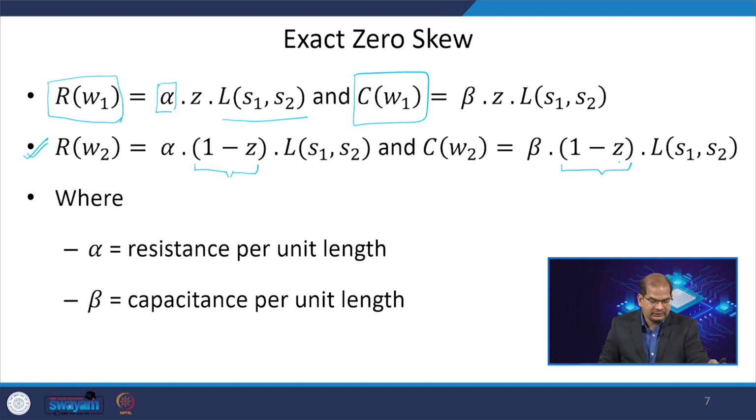So, if you can see this, this is the total resistance calculation, and one concept here is that your resistance is basically rho L by A. So, the area of the metal is constant, it only depends upon the length. What is the length of the metal? Your resistance will scale as per the length of the metal. Assuming that we are drawing the metal, why is it not depending upon the area?